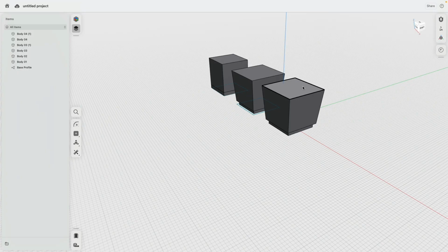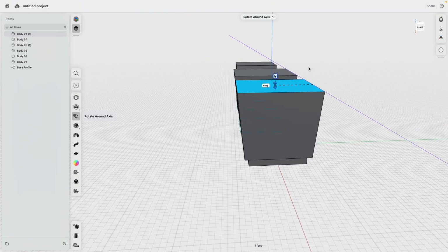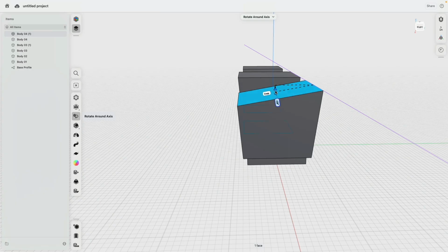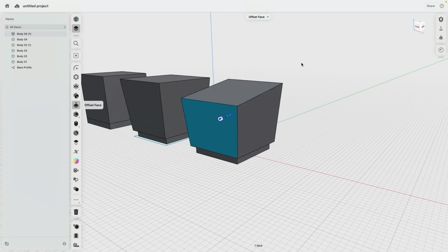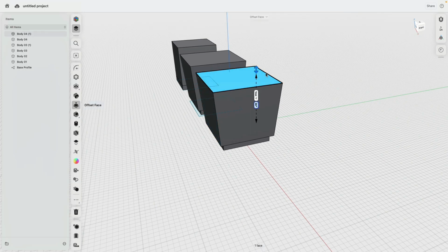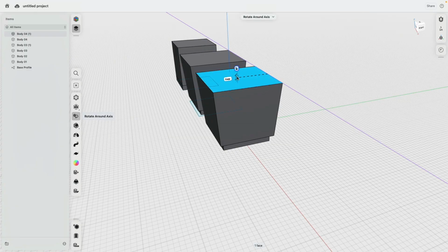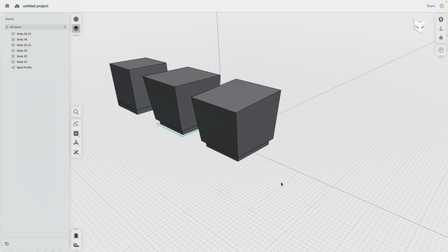We can also rotate faces. That's quite fun. You select a face, you select an edge, and then you can rotate it. It's not really rotating the face so that the geometry distorts. We are only rotating or sliding this face, but all the other faces remain having their orientation. I undo this step, do this one more time, face and then that edge, and rotate this 5 degrees. That looks quite nice.